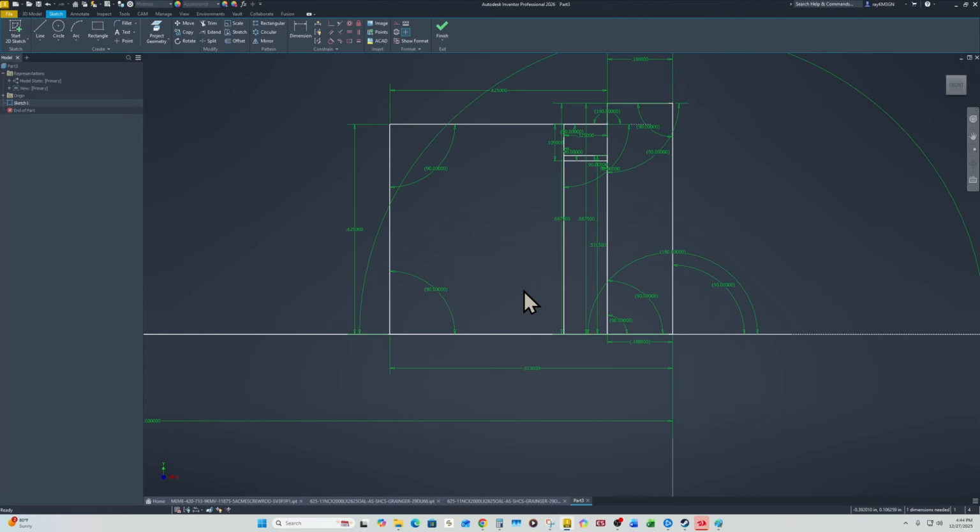So gonna make this big. And we're gonna start in the center, tab 0, tab 0, tab enter. We're gonna go up, 0.531 divided by 2, tab 90, tab enter, tab 90, tab, and let's just make it meet, and it looks good. And we can just make the angles based on, like I said, I usually just go 1/64 above whatever the thread height is.